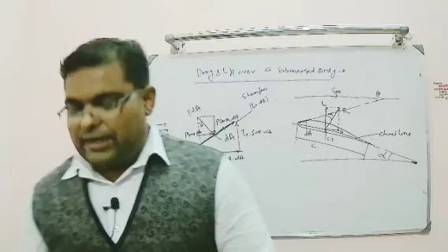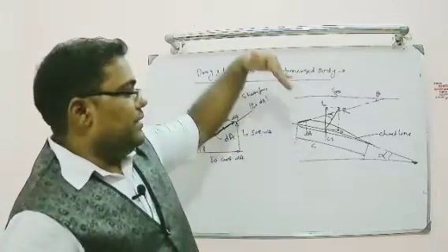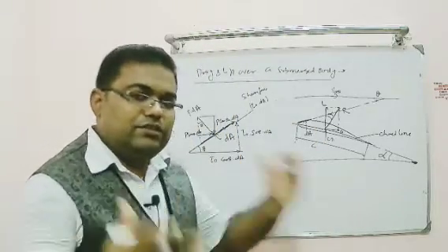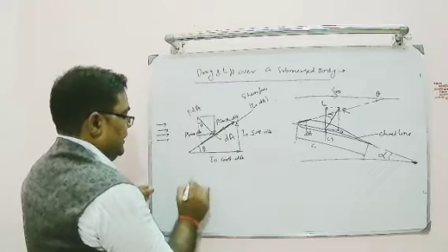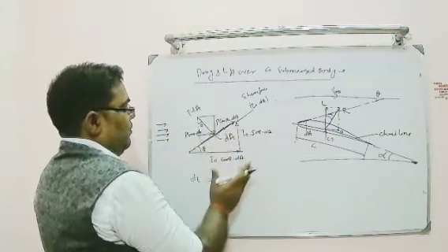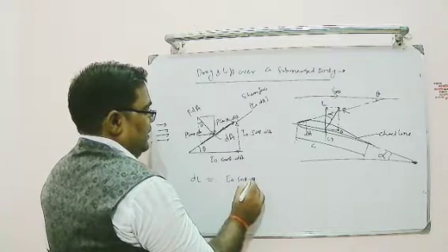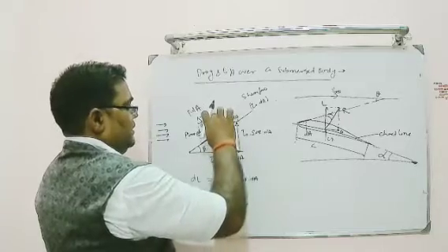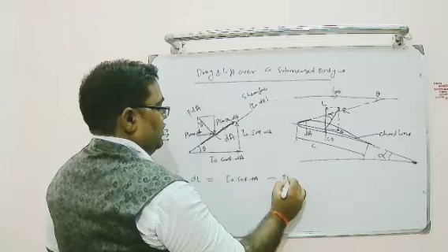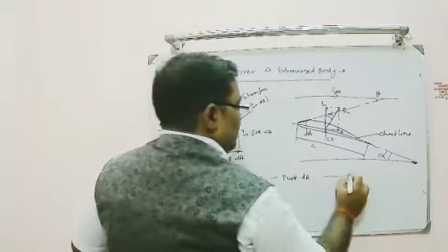Now we will write the elementary lift and drag equations. When we talk about elementary lift, we have to consider all the forces perpendicular to the flow direction. So for dL, one term is tau naught sin theta dA. Another, since this is going down, I can consider in this direction negative, minus P cos theta into dA. So this is the elementary lift, equation number 1.